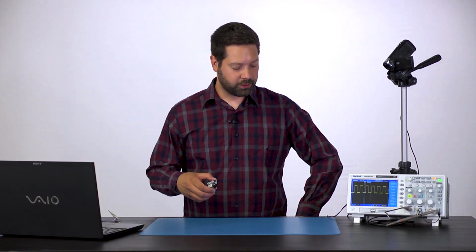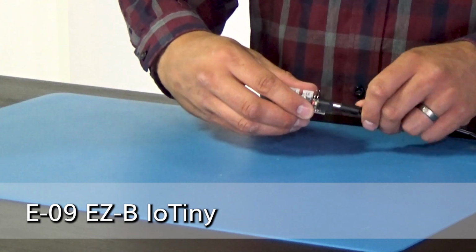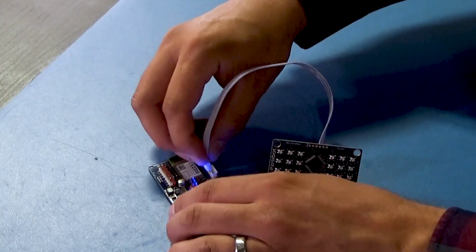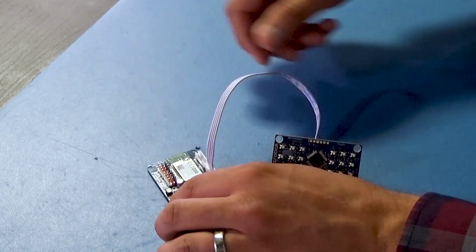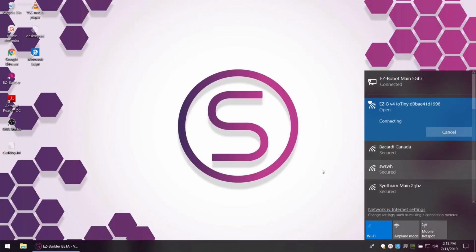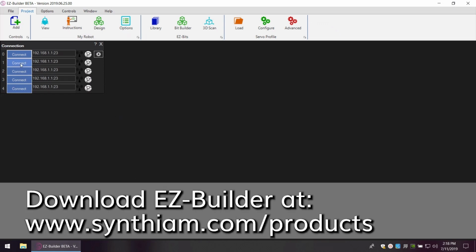Next, let's add the E-64 RGB Eyes to EasyBuilder. First, we'll need an EasyBuilder compatible board. Here's the IO-Tiny. And next, we'll plug in the RGB Eyes into this I2C port here. Let's connect to the IO-Tiny with Wi-Fi. And next, we'll hit Connect in EasyBuilder.